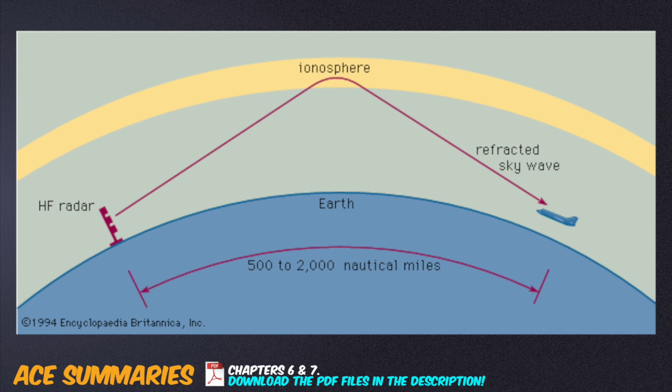In all cases, HF can be received at a station 2,000 nautical miles away, but not one 500 nautical miles away at a given frequency, due to the propagation path. At night, half of the daytime frequency produces the same range due to the higher location of the nightly ionosphere, which is the E layer, versus the daily ionosphere, which is the D layer. High frequency range is also affected by transmitter power, frequency, time of day, season, location, or ionospheric disturbances.